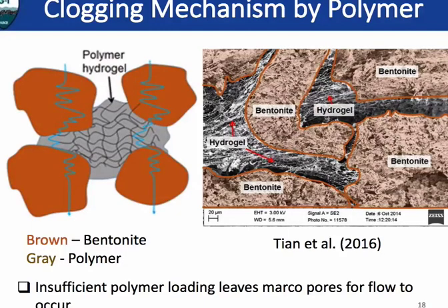When the polymer contacts water, it tightly binds with the water and forms a high viscosity hydrogel that fills up the void and gives low hydraulic conductivity to the BPC GCLs.